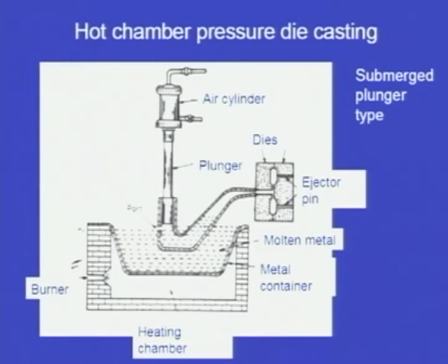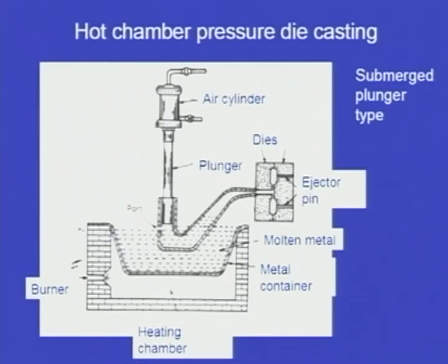There will be a cooling system. Because of the cooling system, the casting will be solidified at a faster rate. After solidification is over, the dies will be separated, and using the ejector pins, the casting will be withdrawn. And here the previous problem is not encountered.